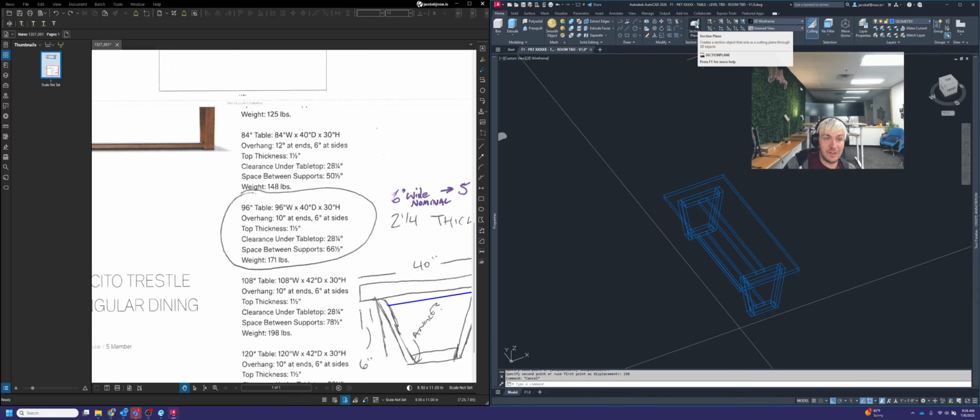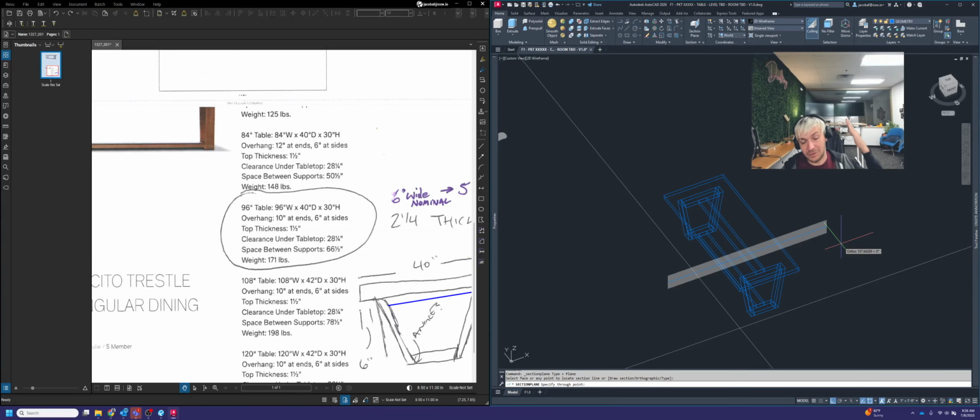And we're going to open up the section plane command here. You can also type it in, but it helps to be able to see that stuff in case you ever need it for anything. So section planes work a lot like the slice command or that 3D mirror command we just looked at. It's going to ask you for a couple of points to draw a section plane. How you want to visualize that is I'm clicking here and I'm clicking here because I'm chopping my model in half at those two points. So that line there is where it's being cut in half.